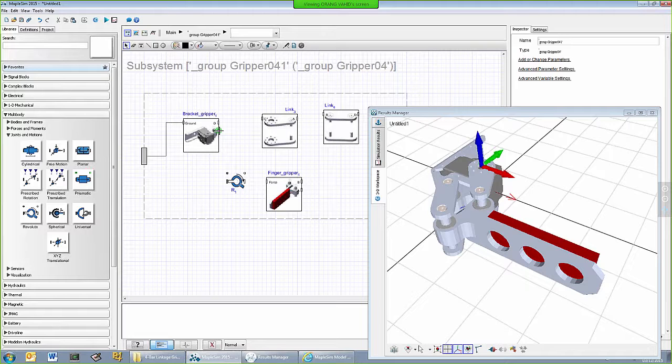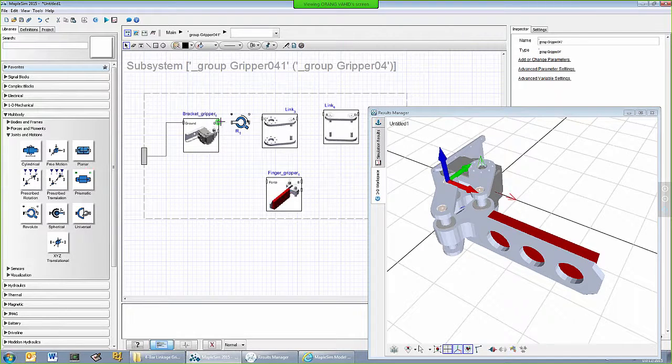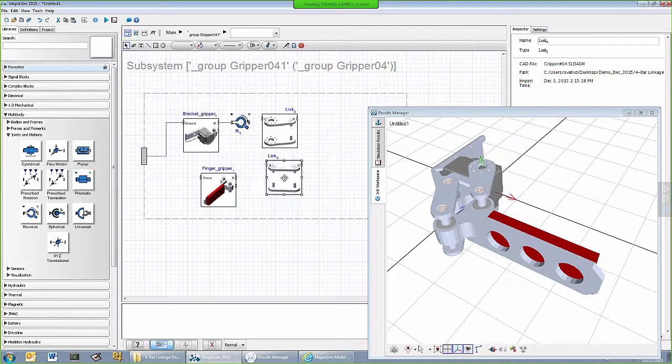And as we see on the construct view, the axis of rotation is Z. So when we bring the revolute joint, it's important that it has the same orientation. It does by default. The default revolute joint axis is Z. So that was D. Connect that first then.